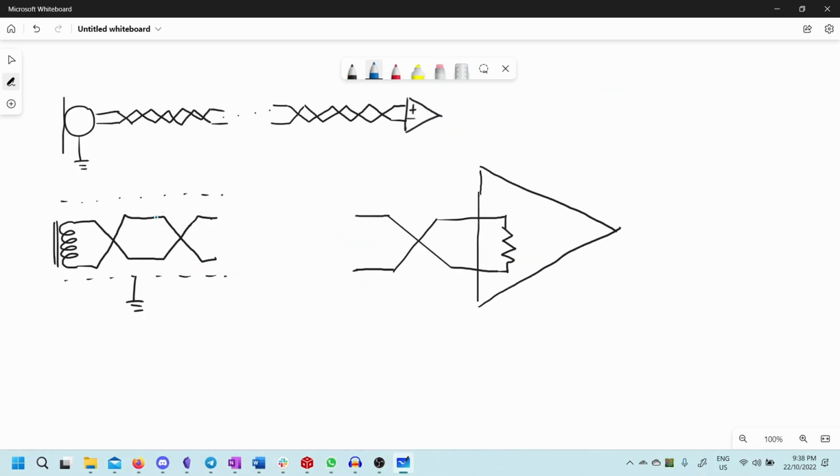that is going to manifest as noise. So inside the microphone is this. There is a coil that has a ferrite or whatever magnetic material going through its core, and when sound waves come in, it vibrates, and therefore a voltage is generated across this point. We'll just call it the hot point, and this point the cold point.